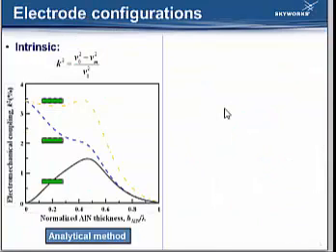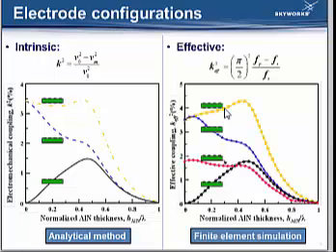Although the approach in this equation, using the open surface and metallized surface velocity, is widely used to evaluate this intrinsic coupling coefficient, it's actually a simplified model, only considering the piezo material property and the electrical excitation boundary condition. In order to take into account the actual potential field, the IDT reflection level, and the mechanical loading effect, here we use FEM simulation to simulate the effective coupling coefficient.